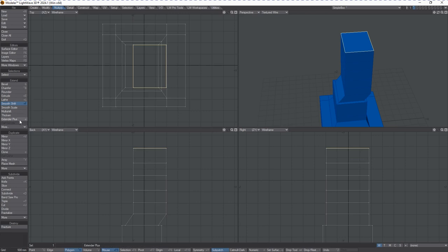Let's do something else. Let's hit T, drop a selection there. All right. And let's say I want to cut this again using the knife tool. So Control K and then, or Shift K and then Control to hold it across so it's conformed. And I'm going to just cut the top of this one more time.